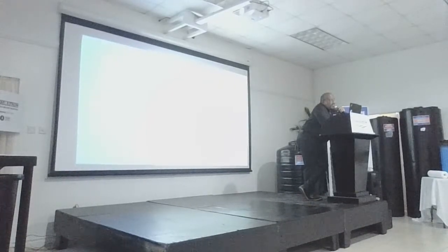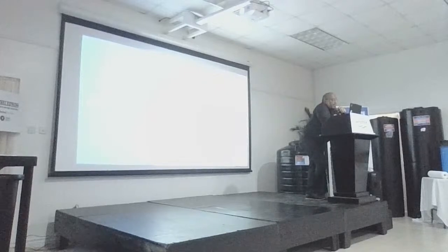So retention time is important in your consideration for a septic tank. You'll see an image here that they have the sludge at the bottom, again, scum. And if it is that the effluent filter, you're seeing way too much matter attached to it, then it's an indication you have problems inside of the tank.